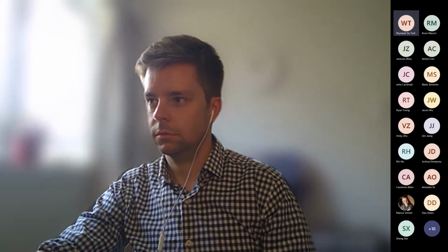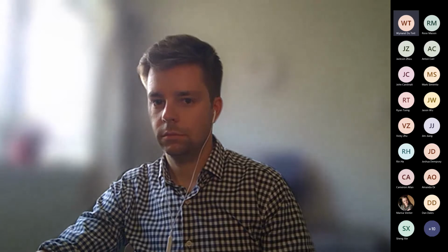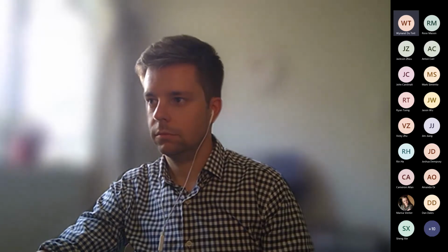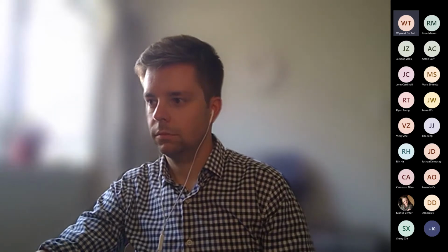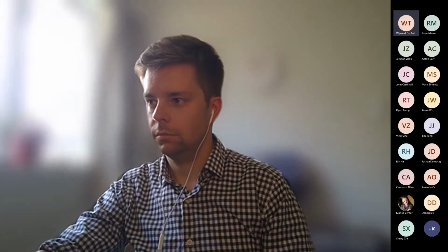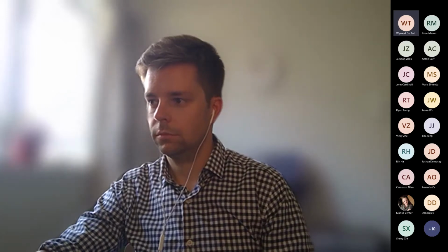Now, on a biofiltration device where you increase the ponding depth, Kevin, thanks for joining. You can add on to this, but where you increase the ponding depth by design, yes, it can be done. There's a couple of practical implications on that, but I think the most important one is, once again, you will have increased conductivity through the media because you have more hydraulic pressure pressing down through the media, which means that you are once again losing a bit of treatment performance.